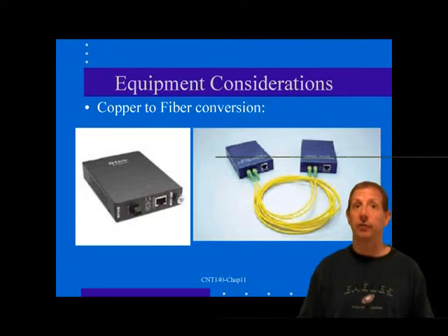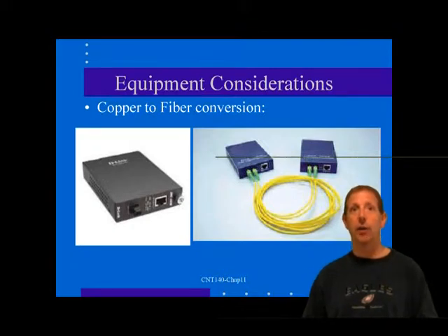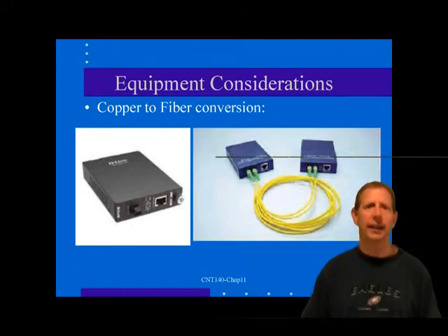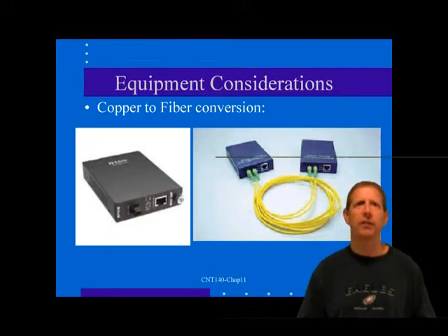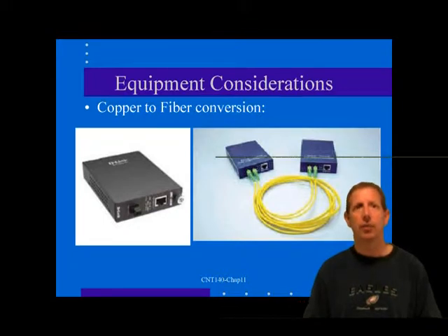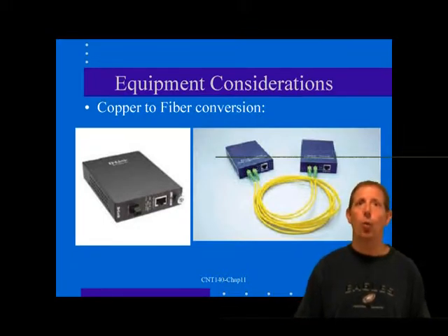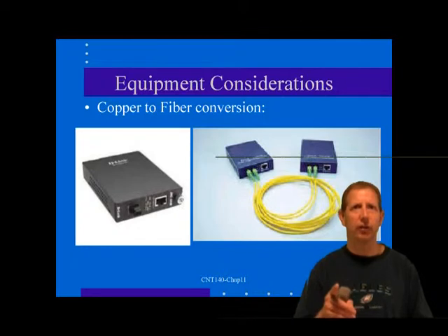You have several options on fiber to copper conversion. At 10 meg Ethernet, you can convert from fiber to an AUI, coax, or 10 base T connection. The AUI, or attachment unit interface, is convenient because the interface includes a power source for a transceiver, which can be used to power the converter. In all other cases, you can expect to use one of the boxy wall plug transformers and a power cord to the converter. Pay particular attention to the type of fiber optic interface on the converter.